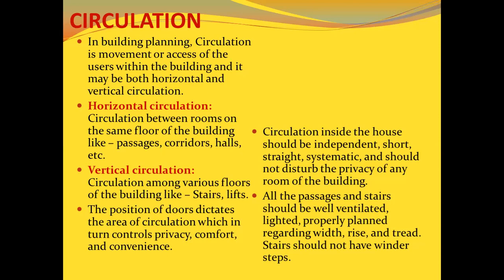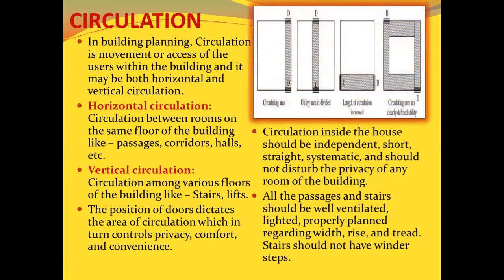The circulation inside the room should be independent, short, straight, systematic, and it should not disturb the privacy of any rooms of the building. All the passages and stairs should be well ventilated and properly lighted and planned regarding width, rise, and tread. The stairs should not have wider steps.